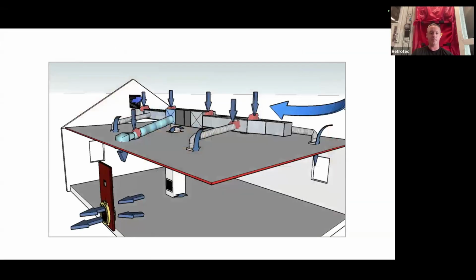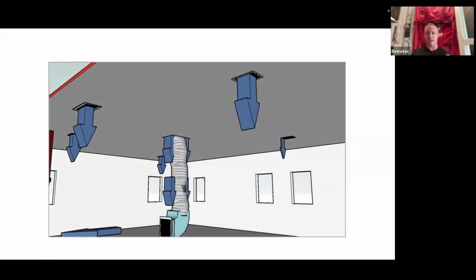So for looking for leaks in ductwork with a pressure pan, this is kind of what's happening as we're depressurizing the house for a duct system outside of the envelope. I mean, that duct system is technically a part of the envelope. When we run a blower door, we're capturing that leakage too in our number. But here, what we're doing is any leakage that comes in from any of the branches, connections, or anything like that, as we put that pressure pan over it, it's really just kind of closing off and completing the envelope around that leak. And that's where we're reading that pressure, that air coming in from the leaks, hitting the box, pressurizing it, and then we can see that it's there.